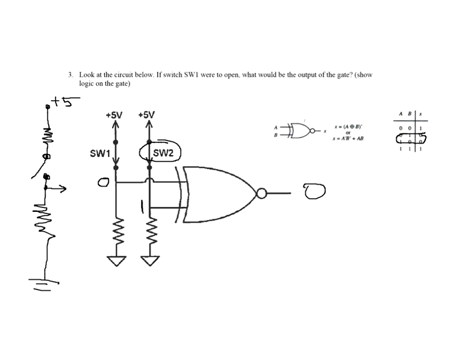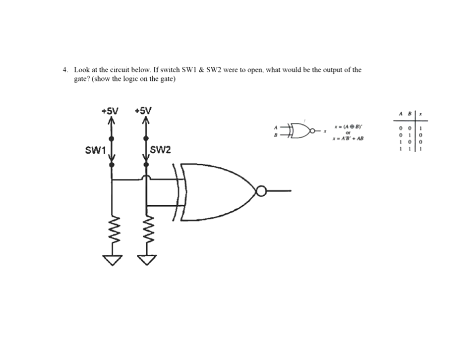I hope we get that. It all revolves around this voltage divider situation here. Sometimes there's a resistor up there, sometimes there's not. Look, this one does not have a resistor in there. This one does. Do not be fooled. Whether there's a resistor there or not, when that switch is closed, I'm going to have a high there. When that switch is open, I'm going to have a low there. Just don't look at the schematic; look at what they're telling you is happening in the schematic. All right, look at the circuit below.